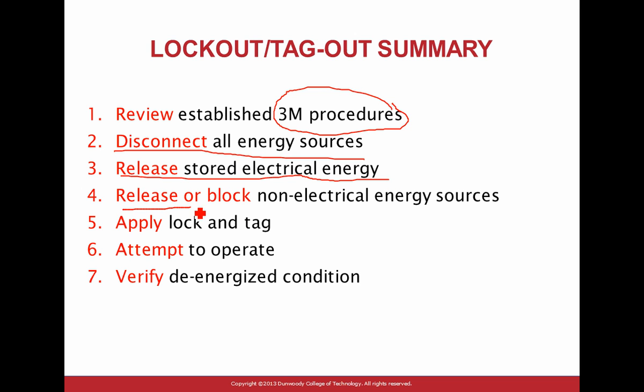And release or block non-electrical energy sources. So non-electrical energy sources, thermal, if you have to diffuse certain thermal things to release it, so while you're working there, it doesn't burn you. So there's other sources of energy. After you do that one, my friends, you're going to apply lockout tagout procedures.